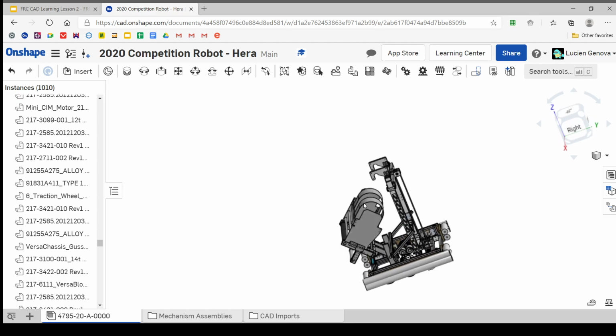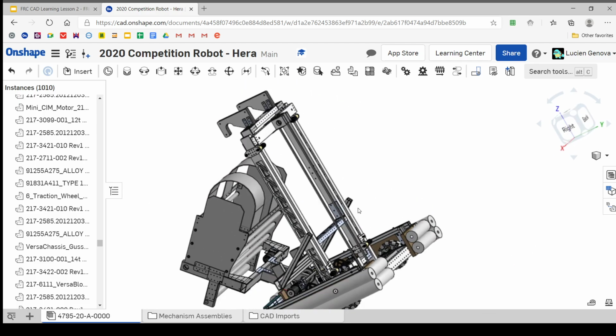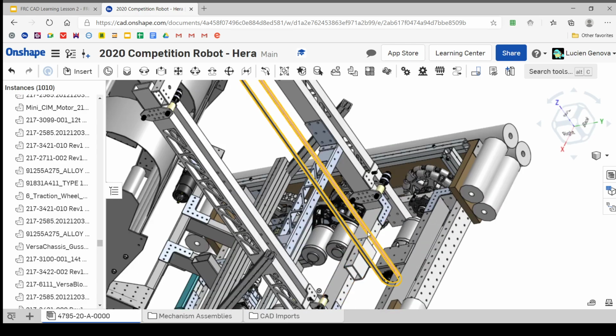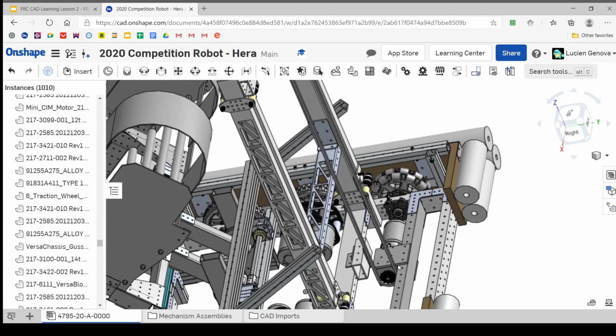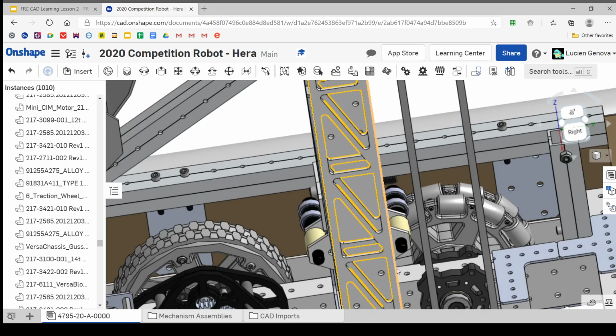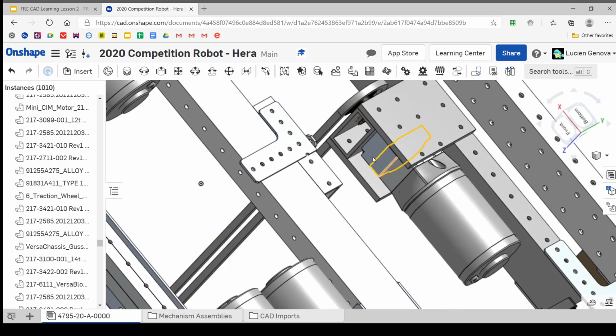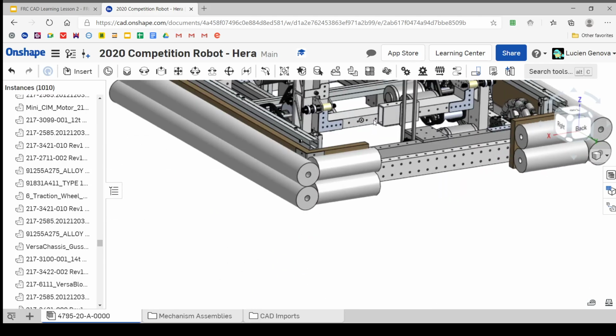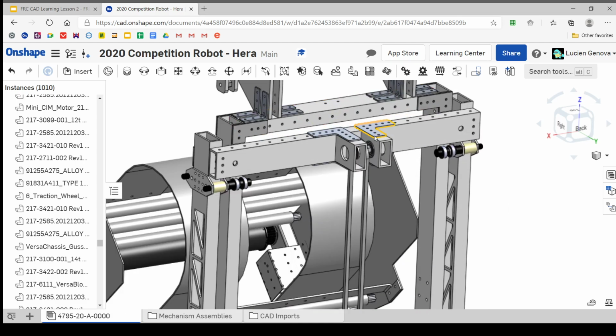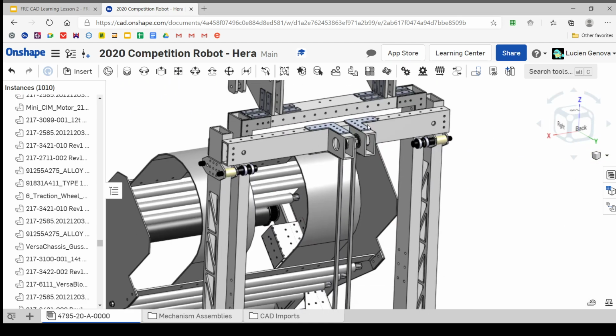And I'm not going to get into how that specifically works. Actually, I will. Basically, you have a chain here, right? Chains in CAD don't really mix, so we just imply them, right? We heavily imply them, leave all the infrastructure in place, and maybe do mock-ups of them. Yeah, here you have a sprocket down here. There's actually a planetary gearbox connected to the motor here, right? You can see you have stages there for your gearbox. Your motor connects in here. You've got a sprocket connects to a chain, which connects up here, but up here doesn't really matter. That's just a coasting thing.